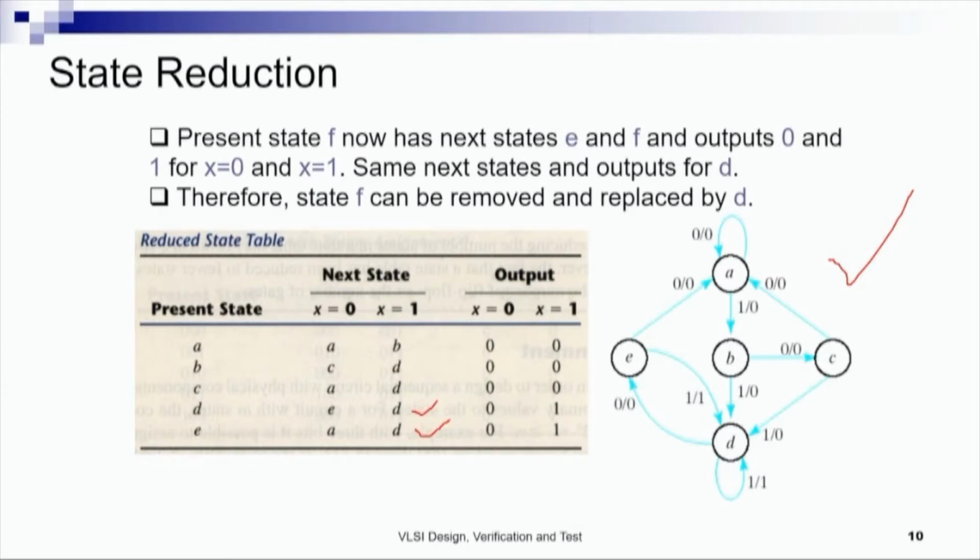The original FSM contains 7 states. The changed FSM now contains 5 states. However, we will see that for all sequences of inputs, it is going to produce the same sequences of outputs, and hence the input-output behavior of both these FSMs is identical.